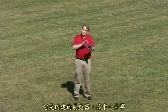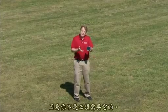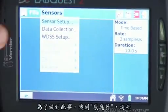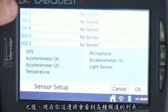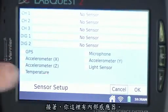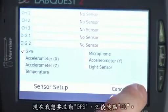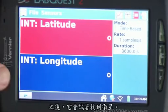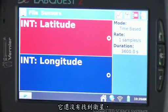So it's a built-in sensor, so one of the things I have to do is to activate it. It doesn't default to coming on because you don't necessarily want it there. To do this, I go up under Sensors, and right here it says Sensor Setup. And so I go to Sensor Setup, and then here you'll see the list of the various channels, and then you have the internal sensors here. And what I want to do is activate the GPS, and when I say OK, it's going to go to the meter here. And so right now it's trying to find the satellites, and so it's got latitude and longitude there, and it hasn't found the satellites yet.